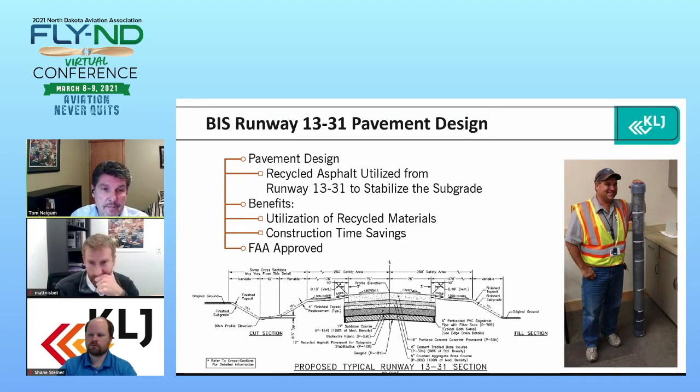And then what we did in that millings is we actually installed edge drains in the millings, because the millings are fairly clean. The water gets through it. And then on top of that, we actually had a fabric, a separation geotextile fabric, followed by 17 inches of subbase.